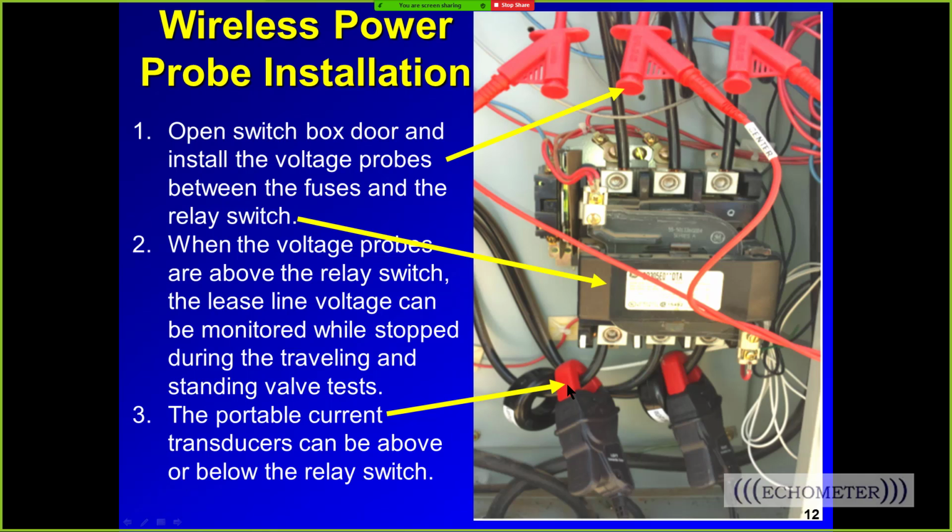This is the one on the left wire. This is the one on the right wire. Notice that the wire goes straight through that clamp. If you came over here and put the clamp facing the same way up, then the wire would be going the wrong way through the clamp. It needs to go facing the transformer that way. And so this one needs to go through facing the transformer.